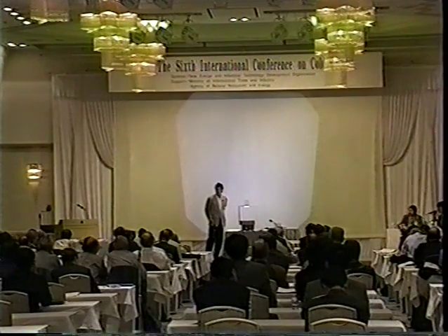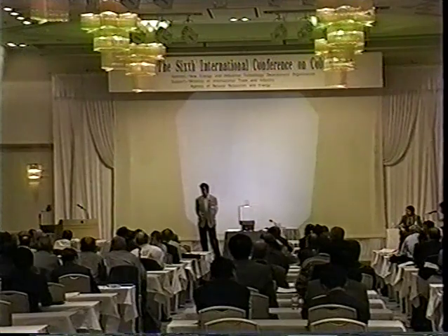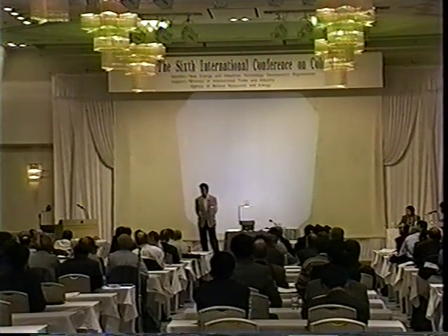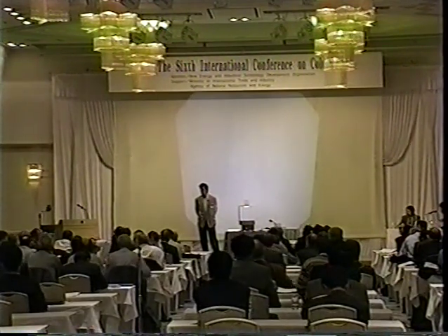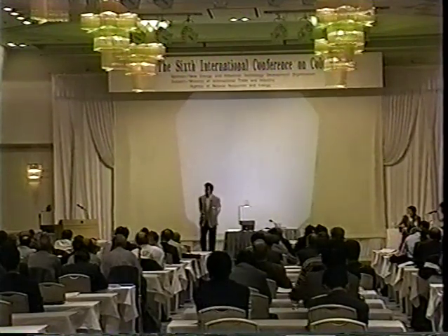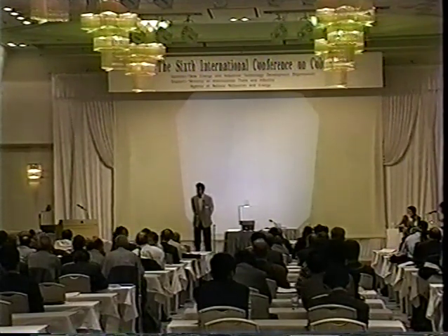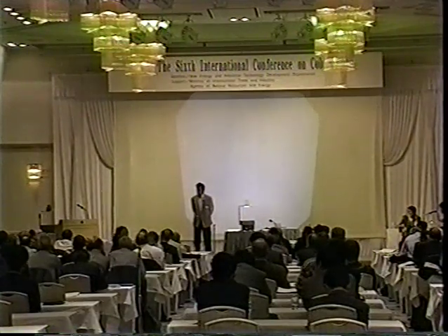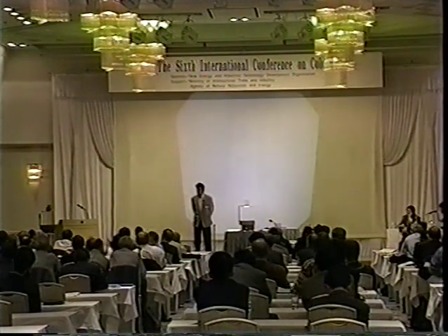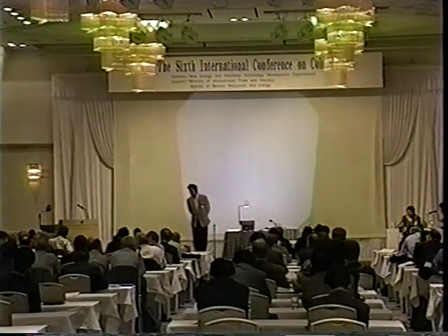Okay, one comment or question. I understood that you believe the elastic energy represented by the curved specimen was somehow useful in producing nuclear reaction, yes? However, that curved specimen does not have elastic energy in it. It only has plastic deformation, because that's a permanent curvature, is that correct? It's not like a spring, you let it go and it comes back again. That represents the stored energy of dislocations. That's a very, very small amount of energy.